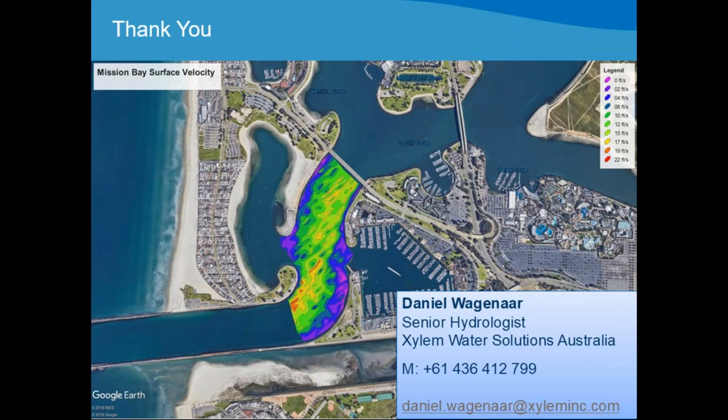But if one or two of the beams are moving away from the group, then you know you have beam separation, and you will have to stop the measurement, clean the instrument, and continue. If that still persists, then you will have to think about lowering the instrument. RiverSurveyor Live does supply warnings in the QA box where it will tell you there's beam separation occurring. If that happens, you need to stop immediately and either clean the instrument or lower it deeper in the water.